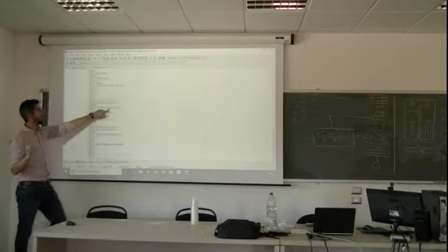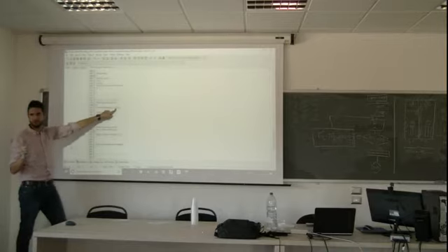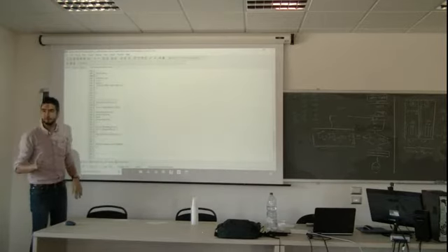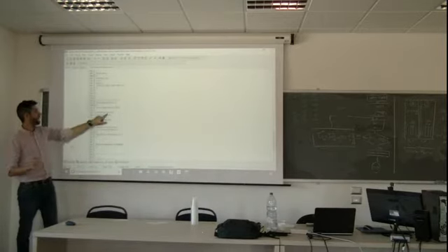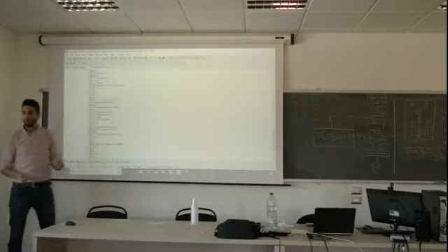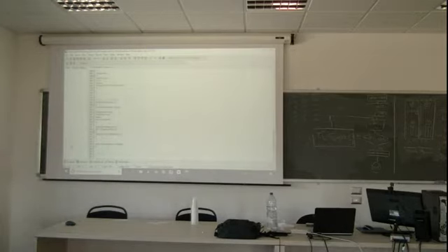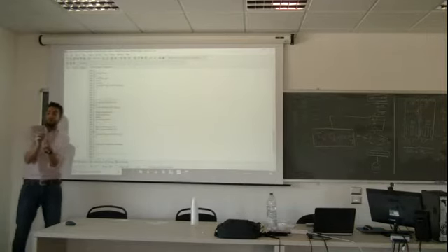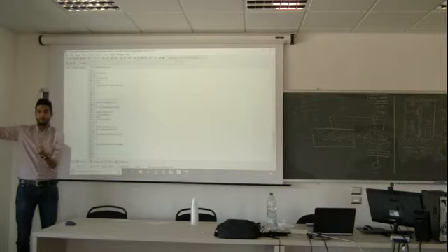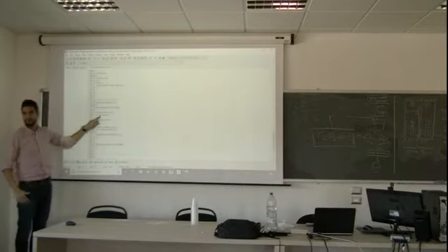The error is the assumed temperature of node 1 minus the solution temperature of node 1. Okay, 23. Is 23 higher than 25? No. Then keep 25. So in this way, after we explore all the domain, we will get the maximum deviation. Because if the node we are exploring has higher deviation than the total that we have computed, it will rewrite. Yes? Does everybody understand? Or should I repeat this?